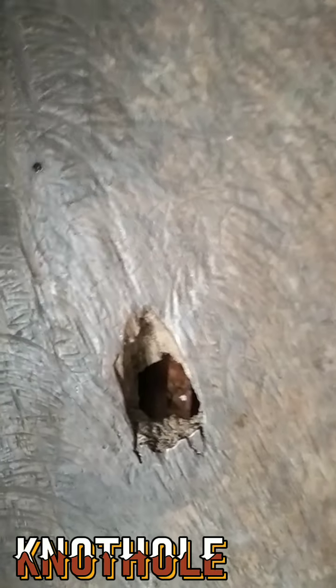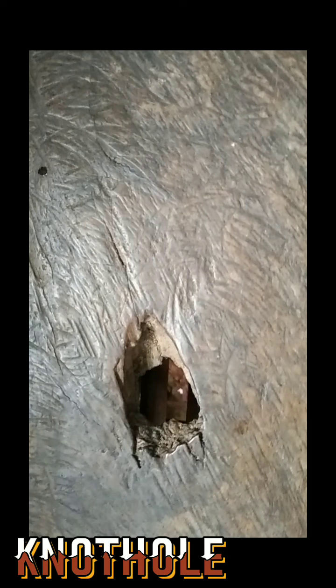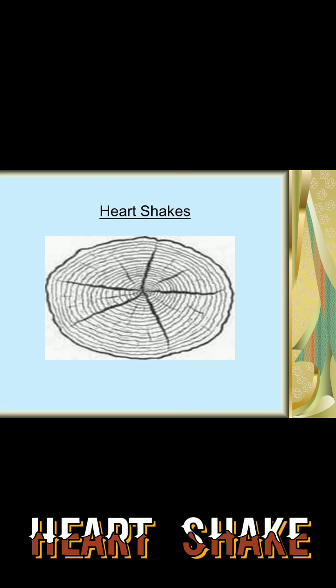A knot that has lost fibrous connection with the surrounding wood can easily loosen and fall out or be knocked out. A knot hole is a naturally occurring open space in a wooden board. You wouldn't want to use a board full of knot holes to build a boat, patio, or fine backyard tree house. A heart shake, a defect in timber consisting of shrinkage and separation of tissues across the annual rings,